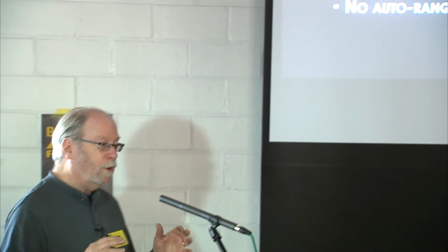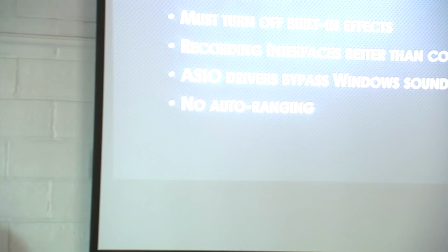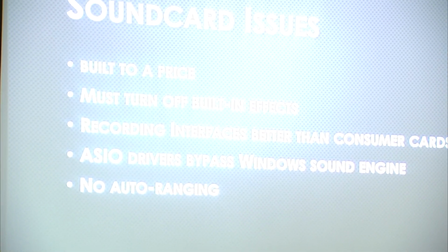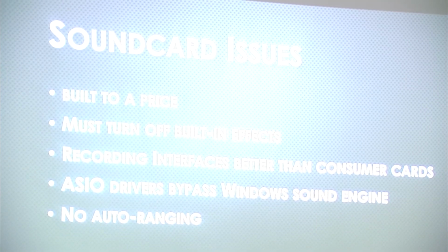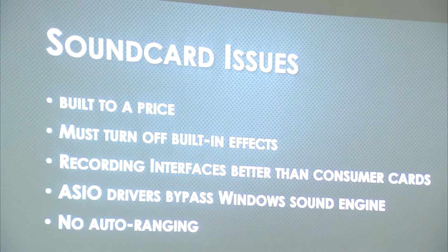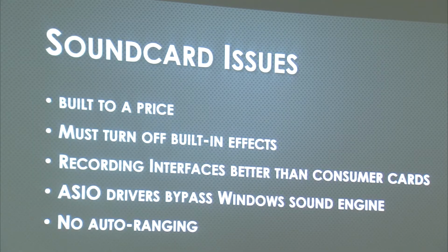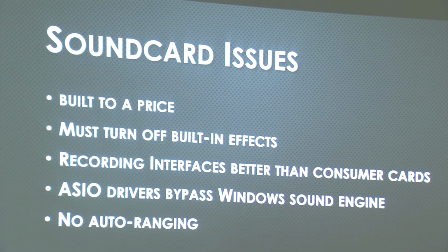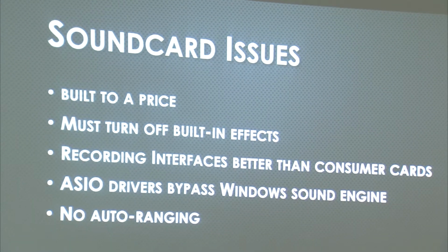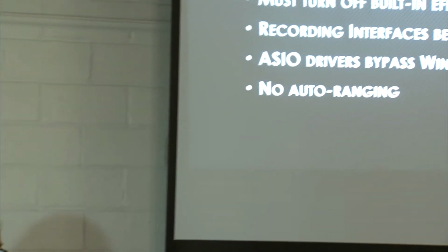So what you want to look for, if you're going to be doing this, you need a sound card that is of decent, recent generation, decent quality. You don't really want the home theater sound cards. Their primary focus has always been lots of output channels. 6 channels minimum, typically 8 channels, and now with Atmos taking off, we're going to find sound cards with 12 outputs, but just one stereo pair of inputs. And on many of the ones I've looked at, the output side will do 192/24, the input side stops at 96. And these are the kinds of compromises they make. They don't really expect you to do much with the analog input. So it's not been a high-level thing.